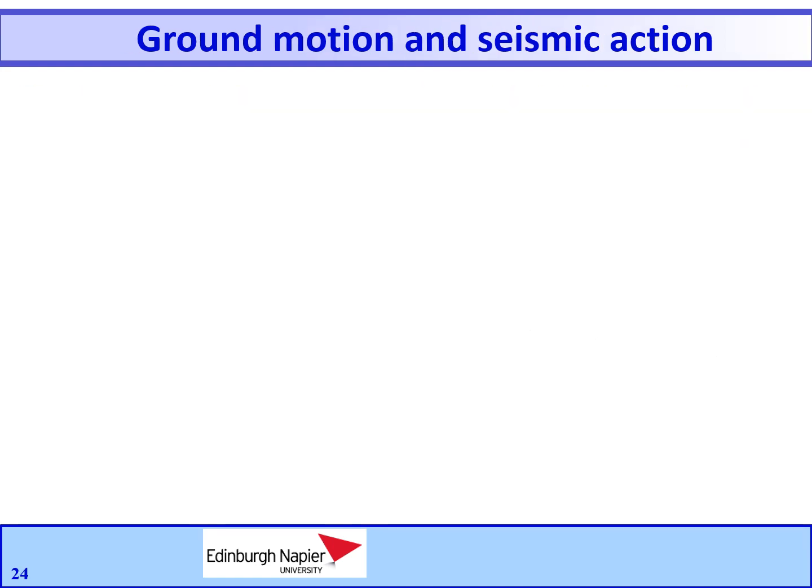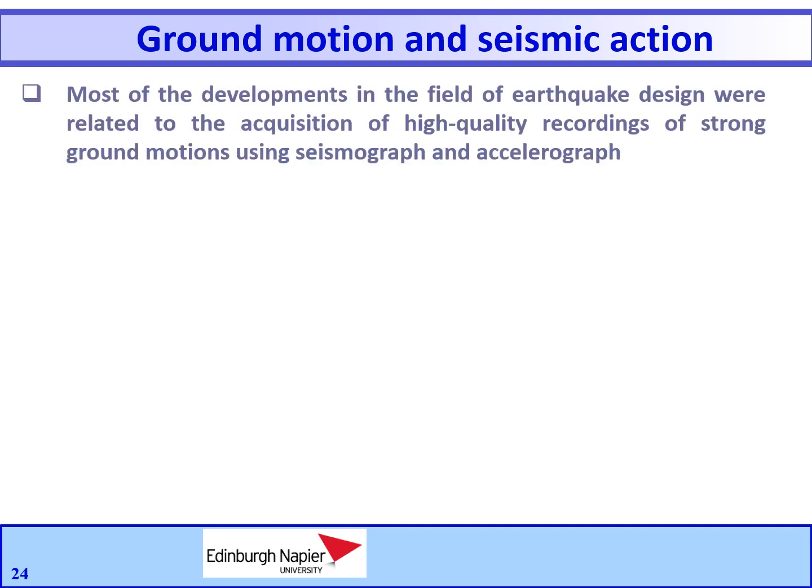Measurement of vibration is of great interest in many aspects of structural engineering. For example, measurement of ground shaking during an earthquake provides basic data for earthquake engineering, and records of the resulting motions of a structure provide insight into how structures respond during earthquakes. Most of the developments in the field of earthquake design were related to the acquisition of high-quality recordings of strong ground motions using seismographs and accelerographs.